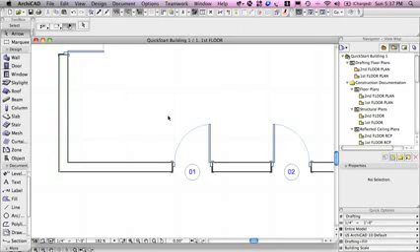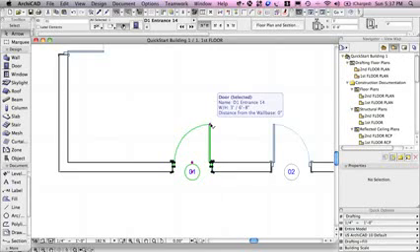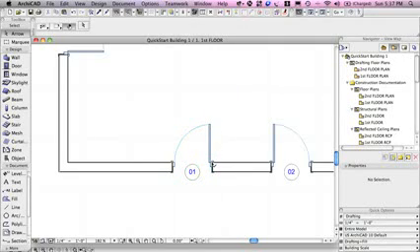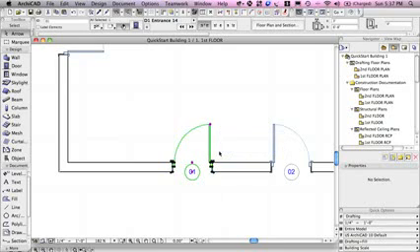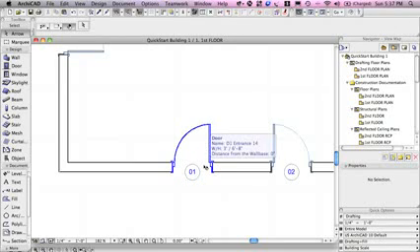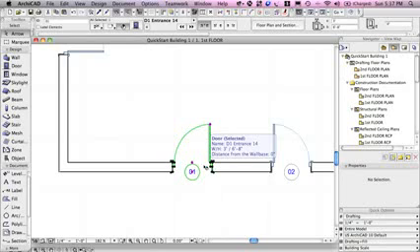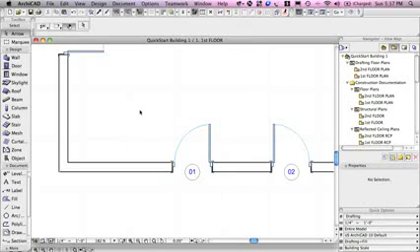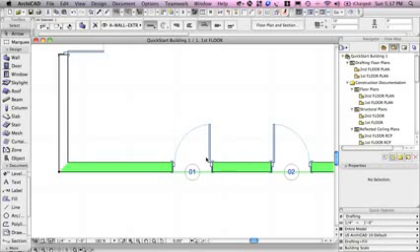and that escape key just canceled the operation. Now to select a door or a window, I need to go either to a corner point, say the end of the door swing, or to the end of the opening here, or depending upon the settings, I can click in the middle of the door opening of the wall. Now the reason I say depending upon the settings is if I have quick select turned off like this, then when I go into this area here, I will not be able to select the door, and in fact it won't let me select doors or windows using the area selection.